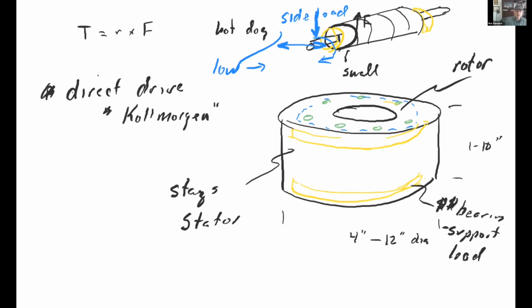I see sometimes where you'll see a 3D printer and they'll have attached a pulley directly to the motor itself. And then they ask the 3D printer to go back and forth. You look at the system and the motor's stationary, and if you're going to cause a mass to go that direction, something's going to push on the shaft that direction. And this doesn't even have a spec for how much you can side load it.